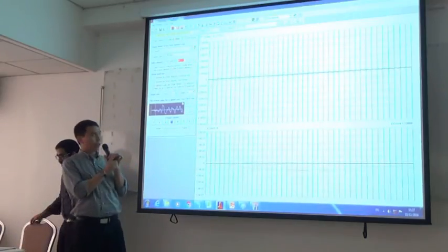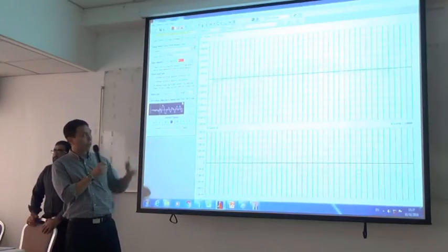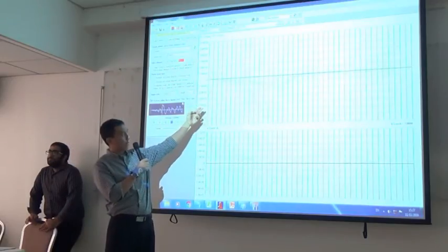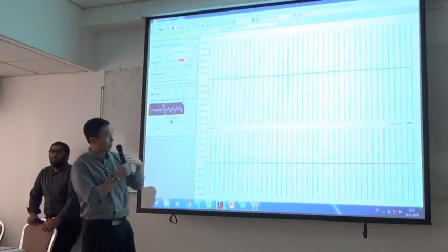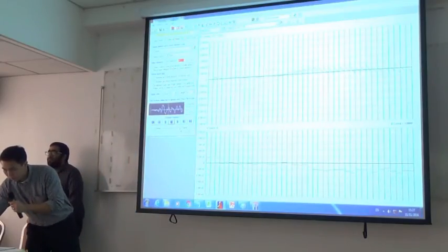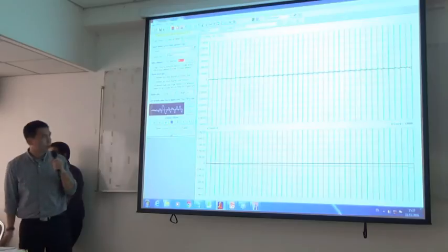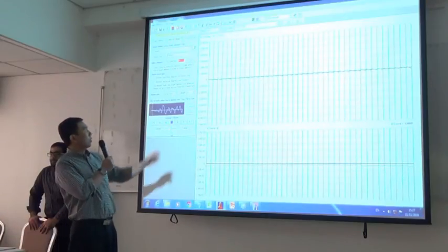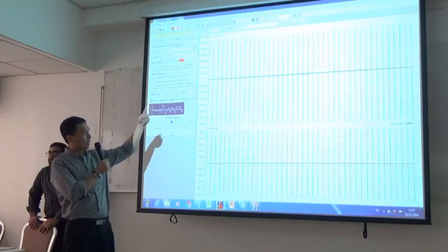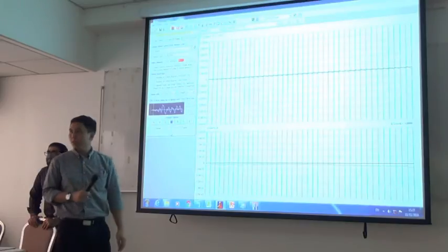Okay, from this diagram, we can see the selected column along the height of the building. This one is the moment diagram. This one is the shear diagram. This 1-2 plane is the moment in the M3 direction, and this shear will be in the V2 direction.